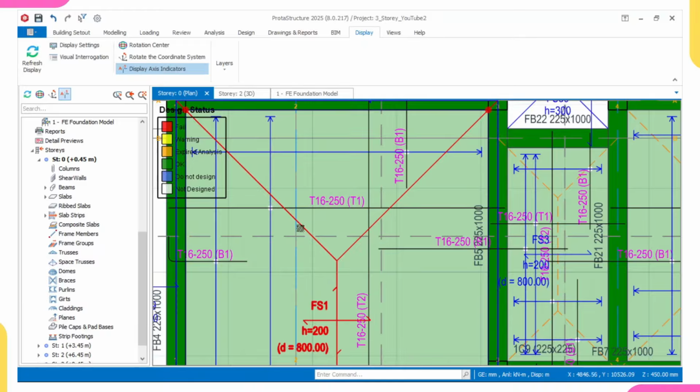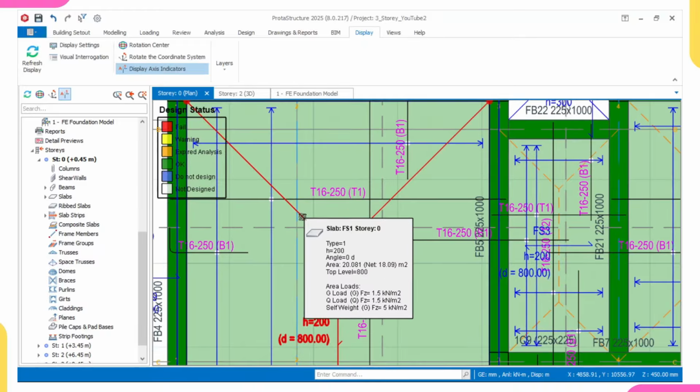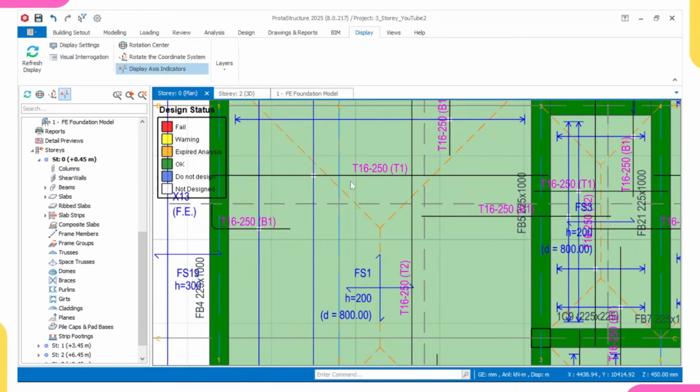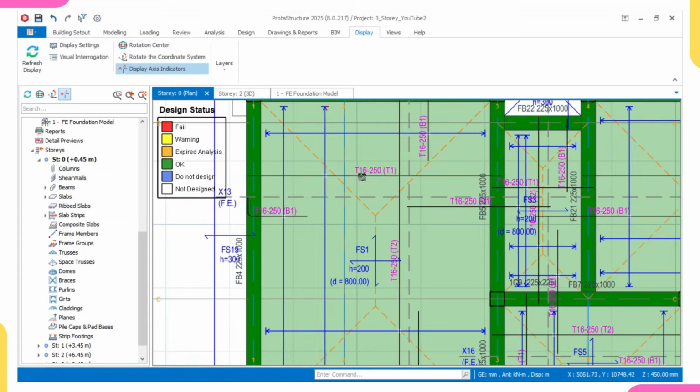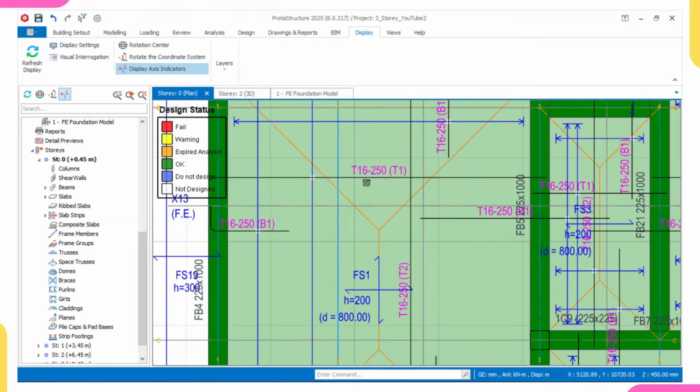I'm located in one of the African countries, which is Nigeria. Once it comes to most of these African countries, they tamper with quality. Yes, their T16 is not T16. Their T16 can be T13, T14, or T15, and thereabout. And the 460 yield strength that we use might be 430, 440, or thereabout, because they are trying to make profit in their production. So for that reason, I'll try to counter that to prevent building collapse.